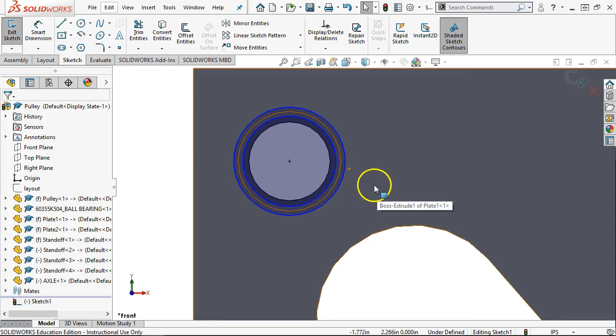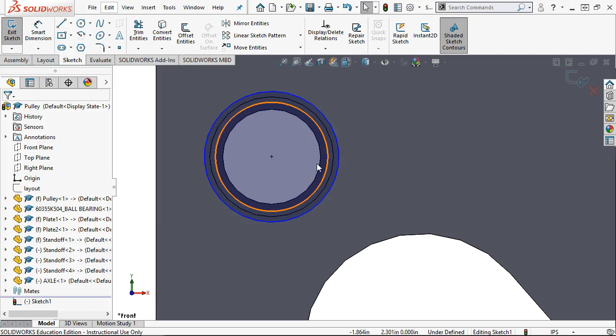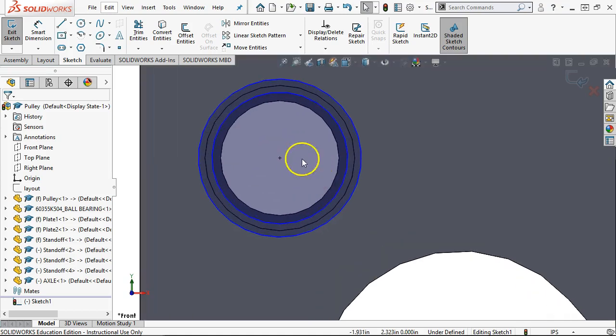So when we are doing this, let me make sure I'm getting my head straight on this one, because we said our default is regardless of feature size. If I don't call out a maximum material condition or a least material condition on one of these, each of those modifiers pulls something else into the mix. If this is regardless of feature size, then we're telling it that the position of that center has to be within plus or minus 5,000ths currently, because we haven't set a position tolerance.